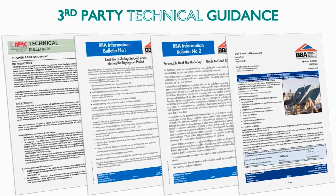Product certificates and technical guidance documents go into a lot of detail about these specifics, and these may include requirements to use vapour control layers at ceiling level or to specify insulation with reduced vapour permeability. Features such as sarking boards or dormer windows may not be covered by the product certification or may impose additional requirements. Even apparently simple things such as the amount of drape required in counterbattens can vary between membranes.